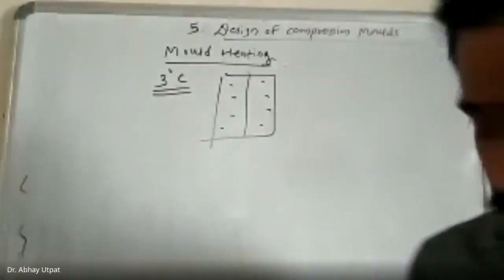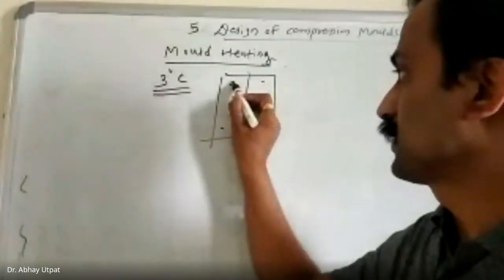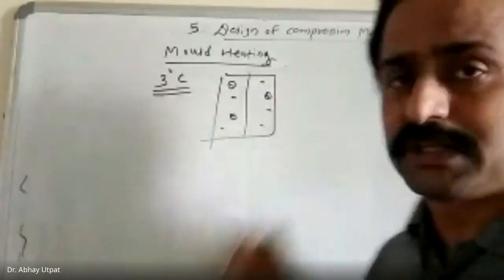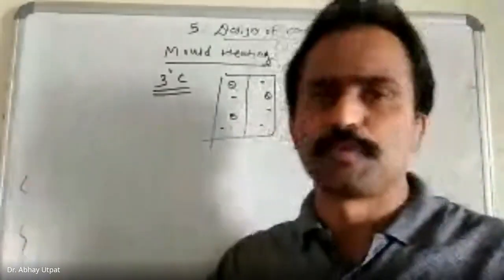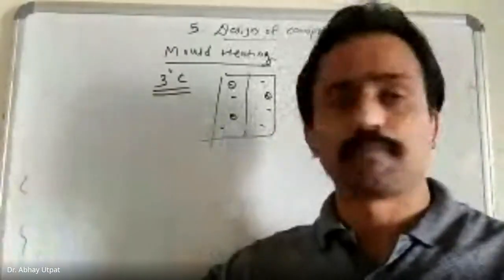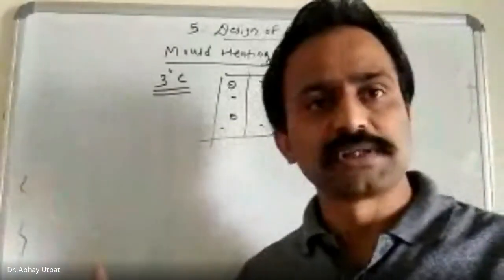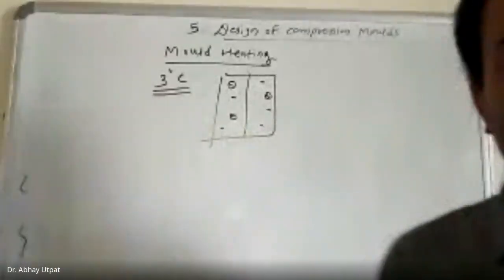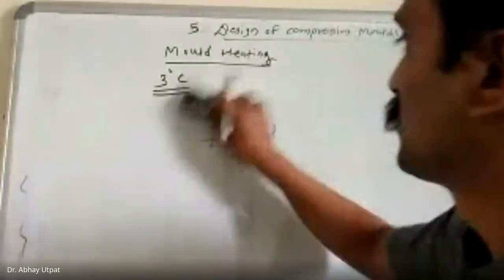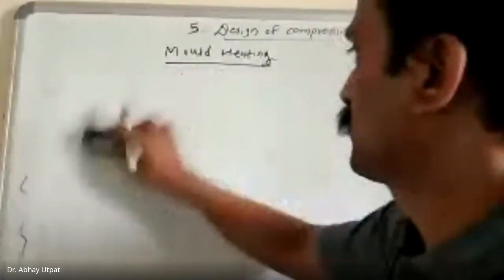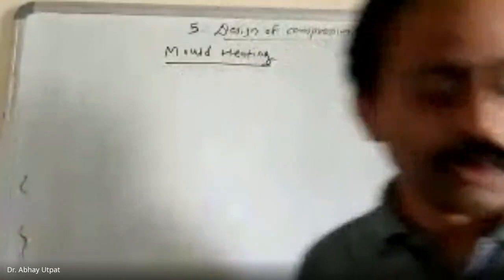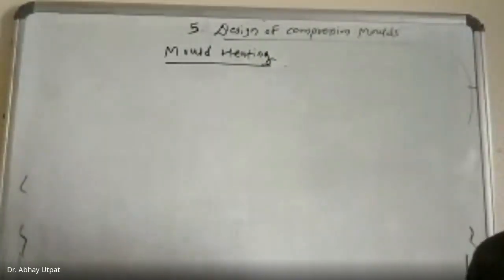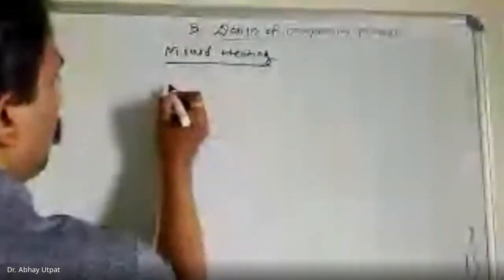So next important thing, the distance. See what I have told. Heating temperature here, here, here. How to measure that temperature? Suppose mold temperature is 100 degrees Celsius. At one point 103, another point it is 97 degrees Celsius. How to measure it? Thermocouples are used. So how are thermocouples located? There is a proper distance to the location of the thermocouple from the heater. See how I am drawing the figure. Just wait.